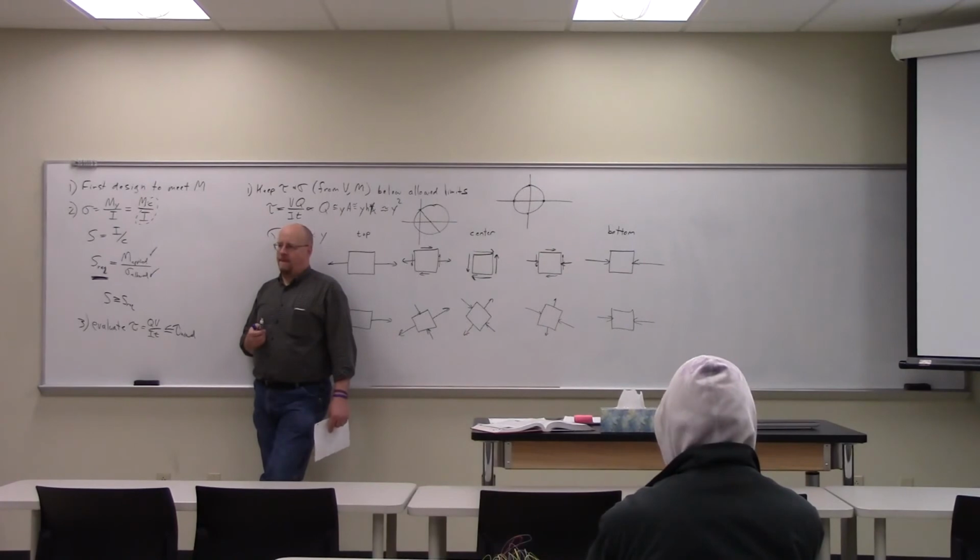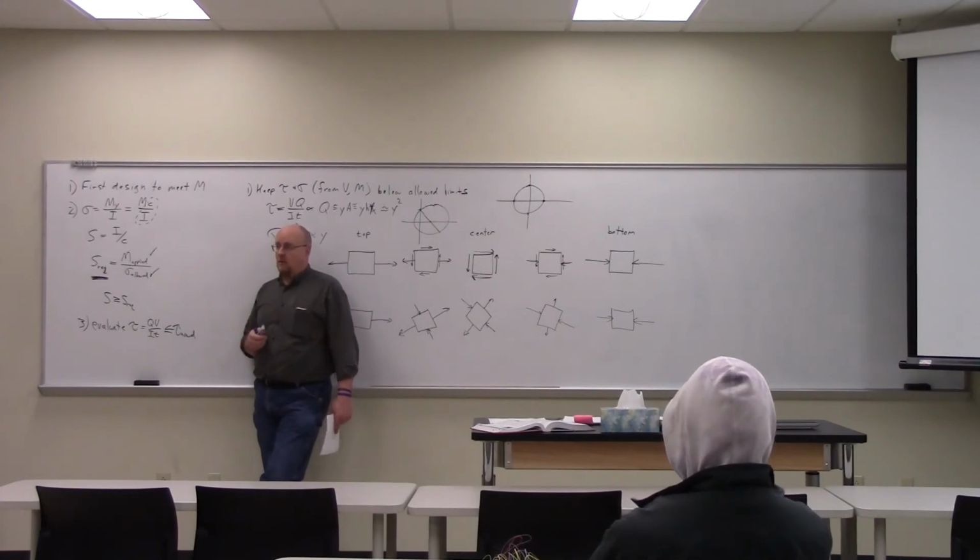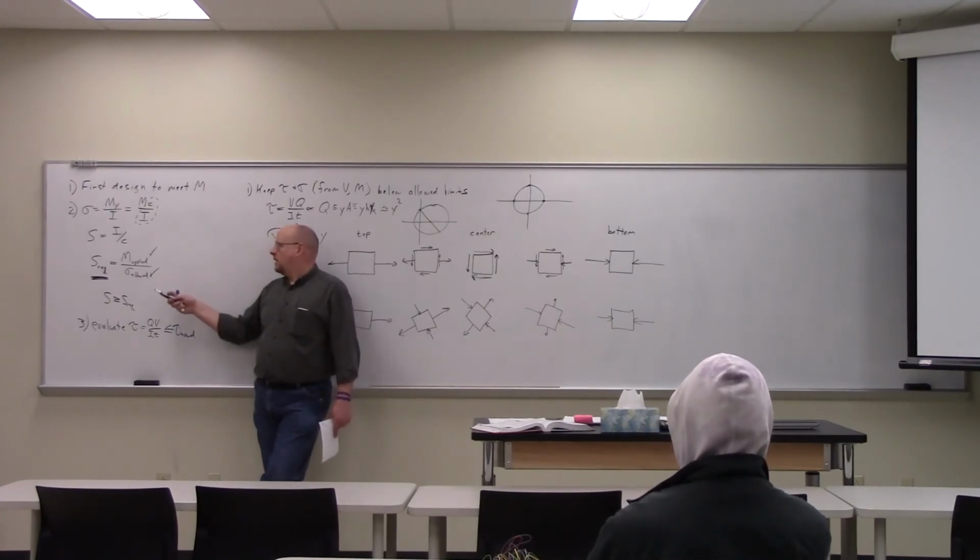Or if you're limited in terms of the design, it's the only thing that will fit. Unless you're limited, then you just need to find something that has a section modulus that's at least as big as the applied moment divided by the allowed stress. And again, sigma allowed is determined by material, so you can actually tweak that as well.